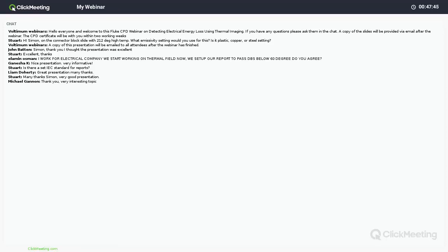Now, they're both very, very similar, and they both say if you've got similar loads, if you've got similar components working on similar loads, you should expect less than a 15-degree difference between those components. You also need to make sure that the DB, the distribution board you're working on, is no more than 30 degrees above the ambient.